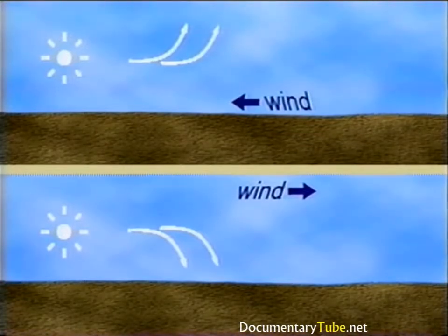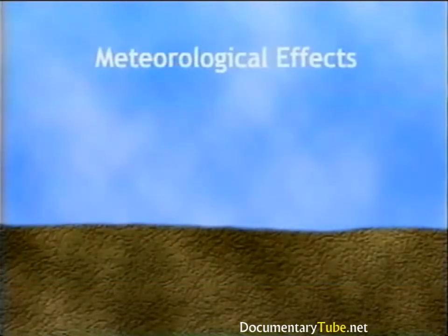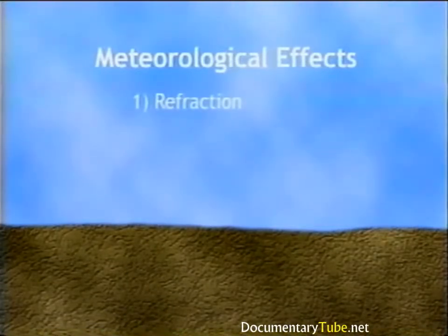The importance of meteorological effects is that sound may reach the receiver with greater intensity if it is refracted downward toward the earth, and with less intensity if the sound is refracted upward away from the earth, than in cases where meteorological effects are negligible. It should be noted that while atmospheric conditions can have major effects on propagation of sound over distances greater than about 100 meters or 300 feet, typical highway studies are performed within 100 meters distance from the highway, in areas where the meteorological effects would be less severe.